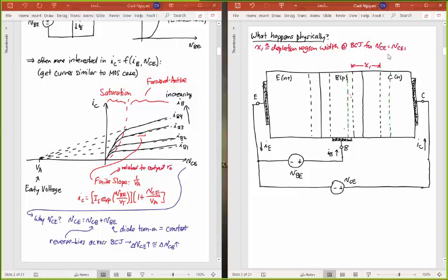And let's say for that VCE1, you know what the current flow is going to be. The current flow is going to be affected by the slope of the minority carrier distribution in my base. So say that slope looks something like this. Say this was the injection point, and then this is going to go down to that point there.